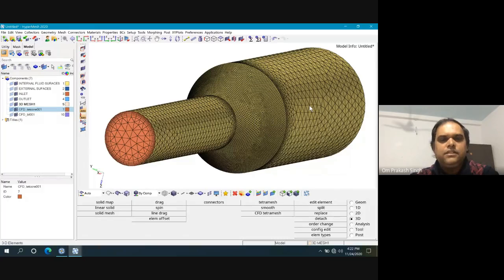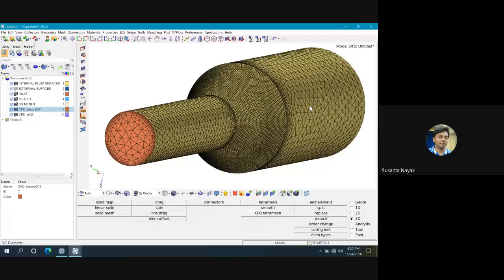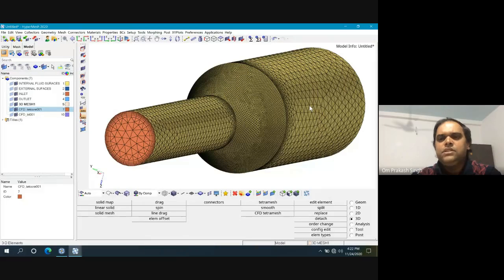See, the boundary layer will not be known beforehand. You can calculate it based upon whatever Reynolds number your problem has. But again, it's always hit and trial. Remember, CFD is not such that you mesh once, get a result, and it is final. You have to do a lot of hit and trial. The first time it will not be correct, so go on to the second, third, fourth iteration. With a couple of iterations and with experience, you will be able to look at it and say whether it is reasonably right or wrong.